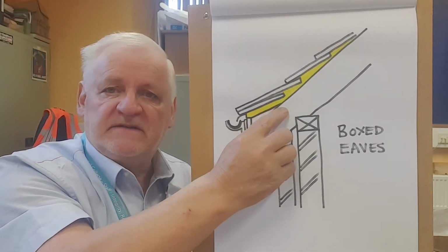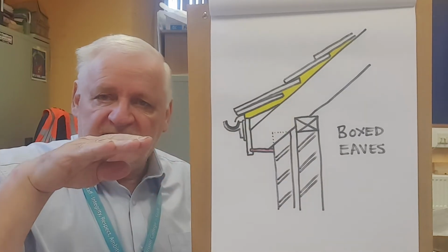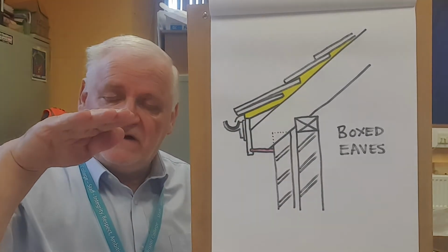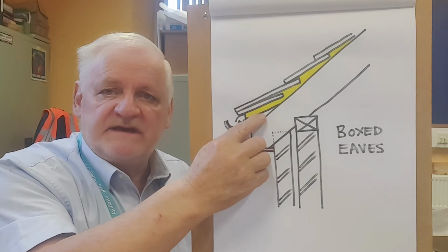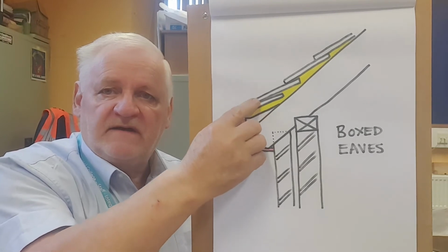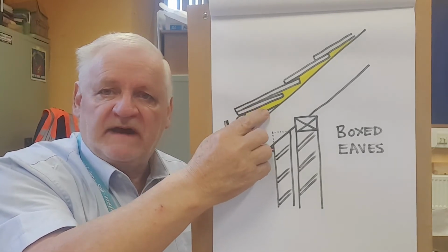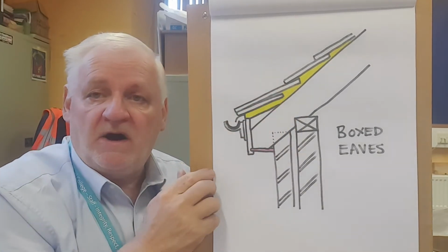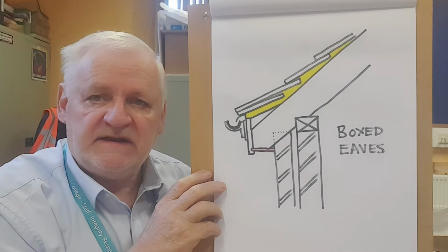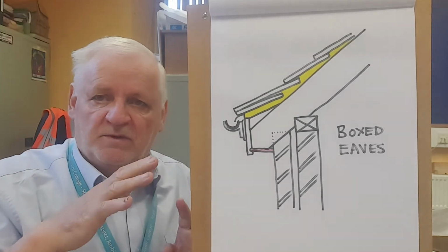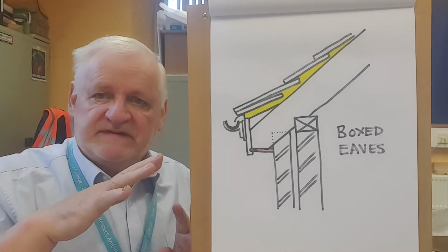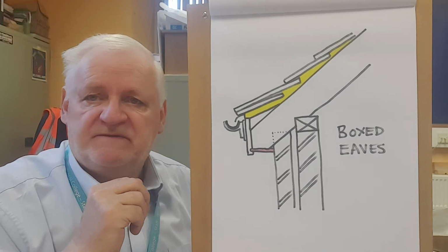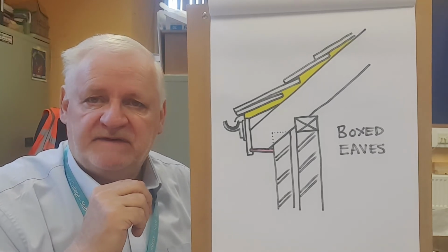This little piece underneath here overhangs the edge of the building, and so do the tiles. Where the tiles and that small fillet overhang, it is filled with cement. Not a hard cement, but a fairly soft cement, because obviously the wood and the tiles can move a tiny bit. We don't want the cement just falling out the first time anything moves.